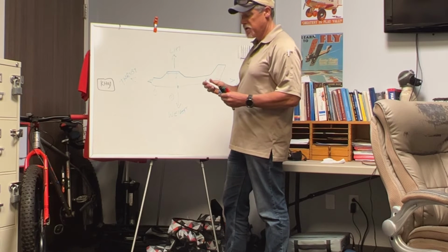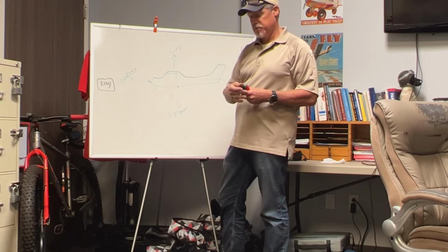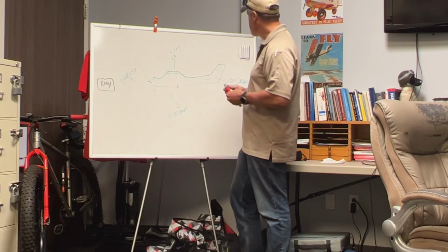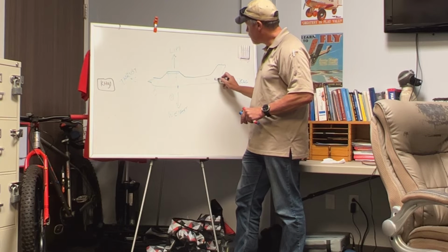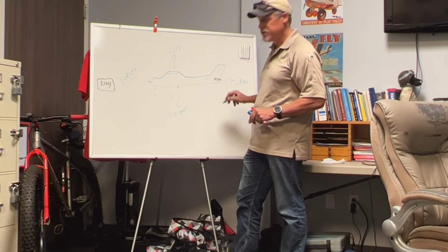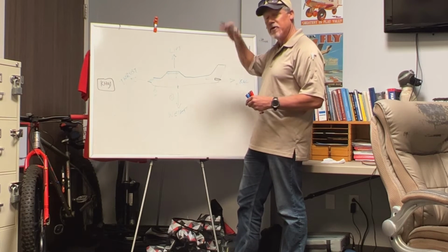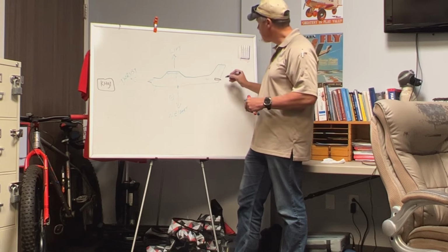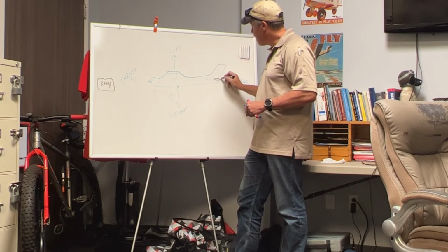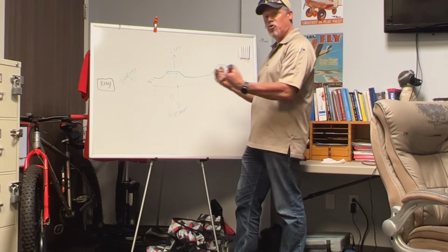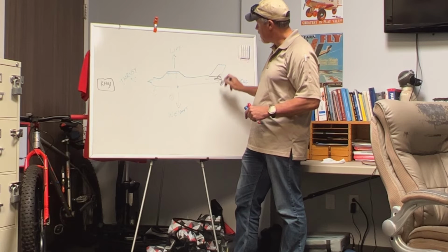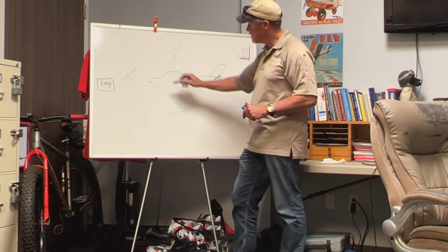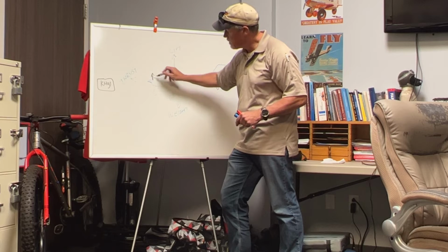Now to go on to what controls the airplane, our control surfaces. We have our control surface here. This is our elevator. So think of an airplane going up and down, an elevator in a building goes up and down. So this travels up and down this way. So when you pull back on the yoke, the elevator travels up, which this force of air hits this, pushing the tail down, which makes the nose go up.